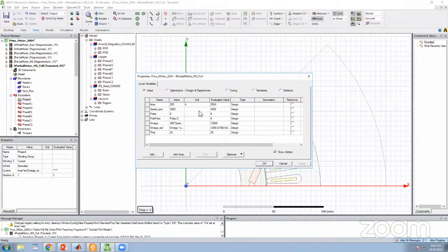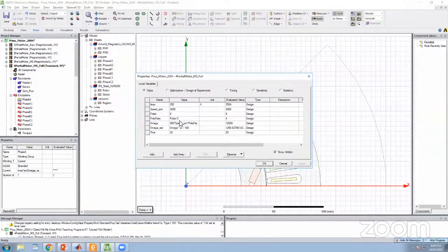They don't have unit. Don't give this parameter a unit, because that will affect your calculations. So for any parameter involved in the calculation, define it as a unitless variable, except the one you are going to assign to the settings. So we can only have I max has the unit amp.